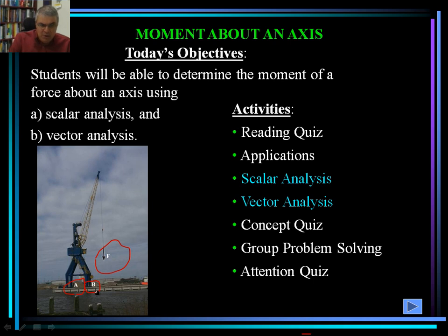It is extremely important for such a machine to not have any overturning moment, otherwise it's going to simply tip over as a result of the applied force. So when designing such a machine, we always make sure that we check for the applied moments. We look at different scenarios, different cases, and we look at the worst case scenario, and we design for that to ensure the proper operation of our machines.